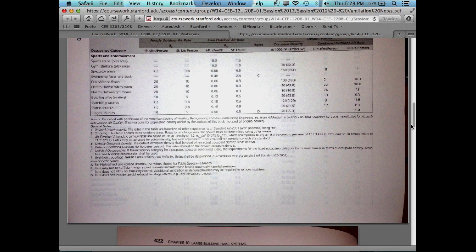Like, that's what this building does. If you've ever been in here late at night, sitting in one of the atriums, like the green atrium, at 2 o'clock in the morning, there's this incredible suction that comes through that can pull the paper right off the wall. What's happening is we're doing something called flushing the building, where up at the top of the atrium some vents have opened up, and on the side walls vents open up too, so that just convectively, all the heat starts rising out of the building. And it really does. It'll pull the paper right off the table.